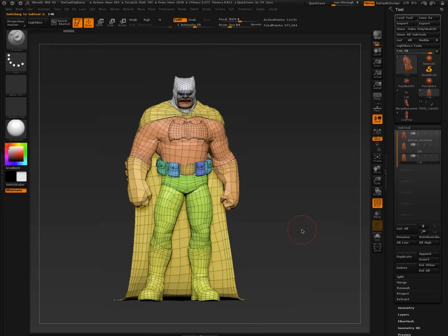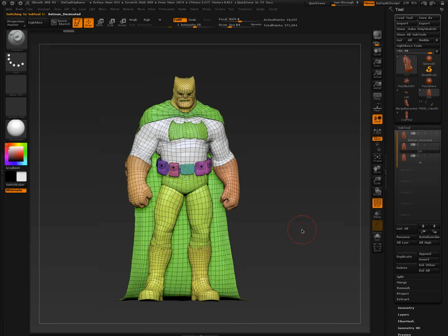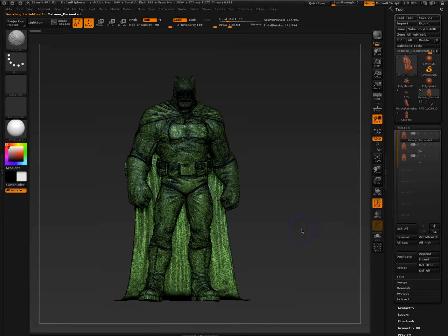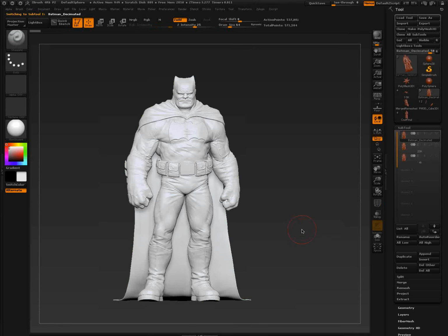Then I went even lower, which is on our site, but this gives you an idea of a workflow. You can import your meshes from Rhino, SolidWorks, Matrix, or wherever else you're working, even if it's all triangulated. If you're doing something from Freeform, anything like that, you can bring that in and then use the ZRemesher. So let's get into the ZRemesher so you can see the features and how all this experimenting we were doing as we were developing would work.